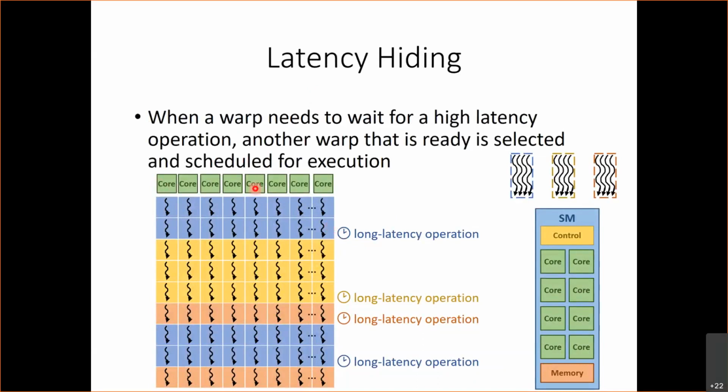So there are these cores, right? And these cores are pipelined. When you studied pipelining in a basic computer architecture class, you saw how when an instruction reached the point where the next instruction cannot execute before this instruction finishes waiting, we added stalls into our pipeline. So basically, instead of adding stalls into our pipeline, what we do here is we remove the thread and bring in another thread whose instructions are independent of the other thread that was executing.